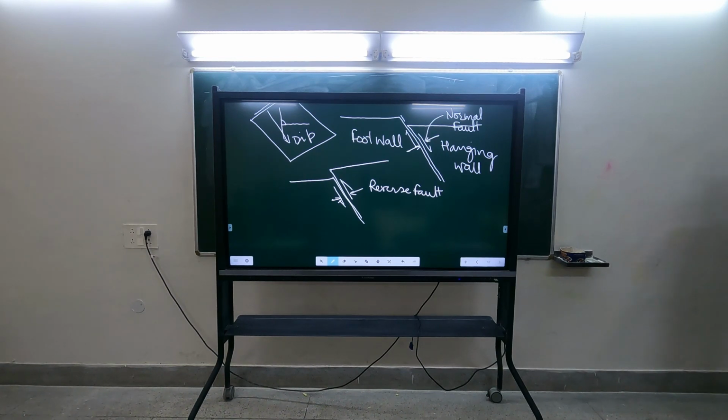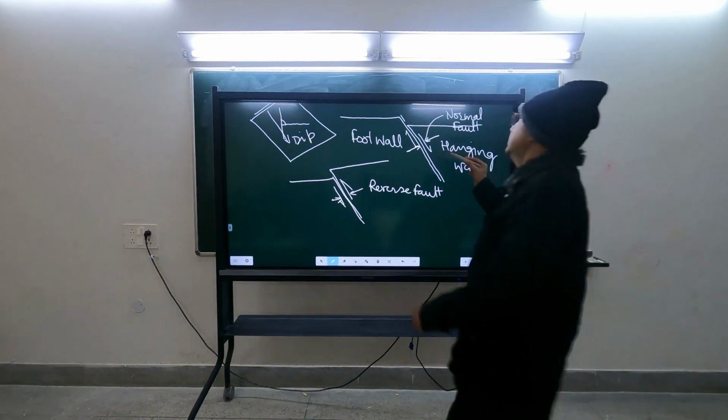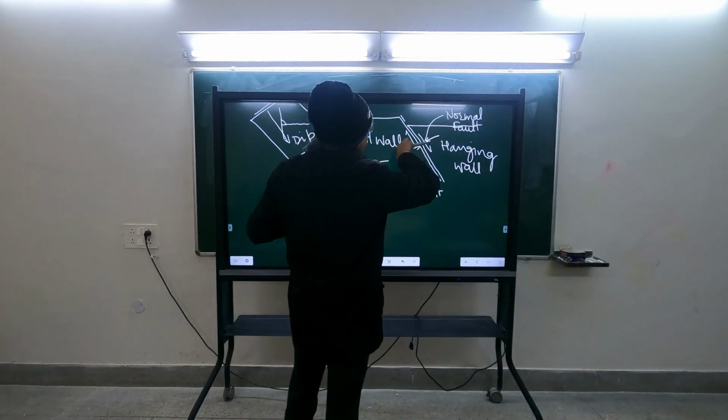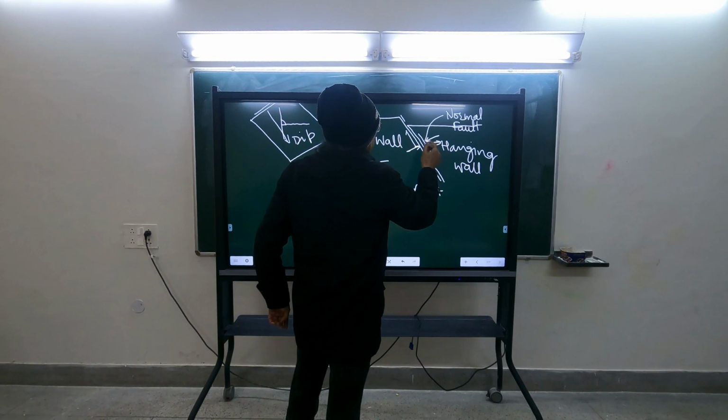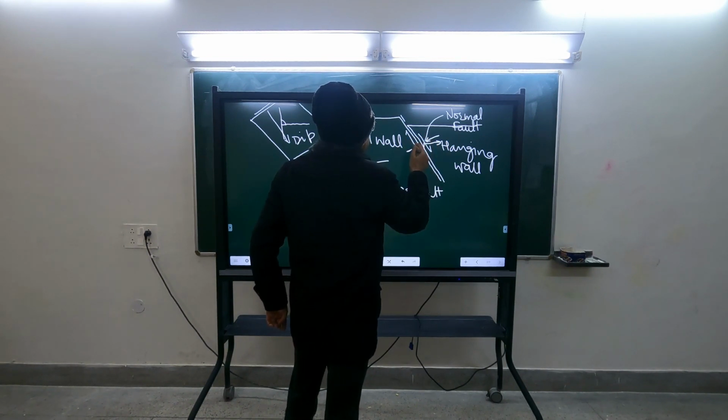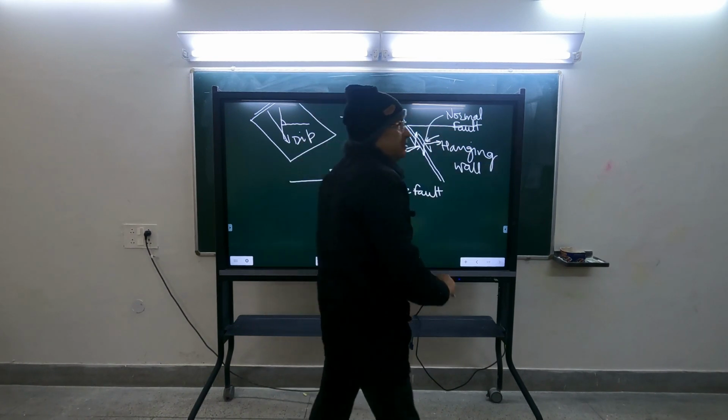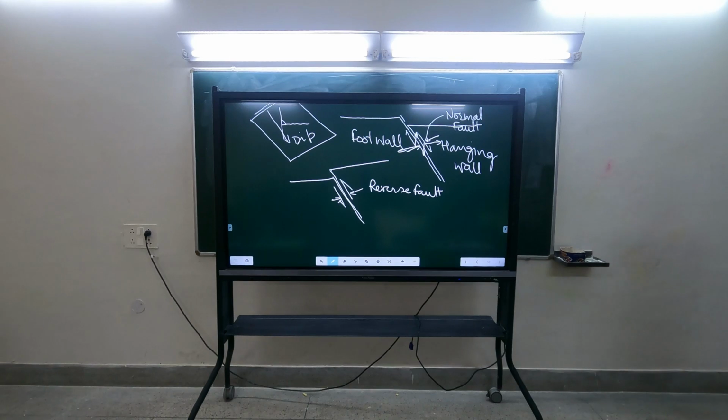When you are pulling it, there is a force in this direction which has a vertical component upward, acting against the gravity. So the net normal force is reduced, and due to that the friction is also reduced. The same thing is happening here. When the shear force is acting like this, if you resolve it in horizontal and vertical directions, you can see there is a component acting away from the fault. So the effective normal stress is going to reduce at the fault.